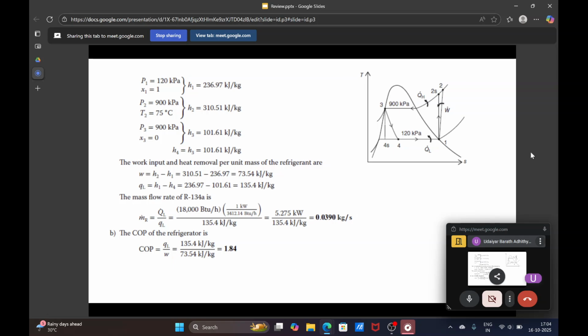If you plot this vapor compression cycle on a TS diagram, this is your vapor dome, and these are your two pressure levels. A pure fluid boils at a constant temperature, so a constant pressure is also a constant temperature. So you have constant temperature here lying inside the dome, and if you draw an isobar, this is how it looks. It extends close to the liquid dome, and then it enters the vapor dome, and then there's boiling.